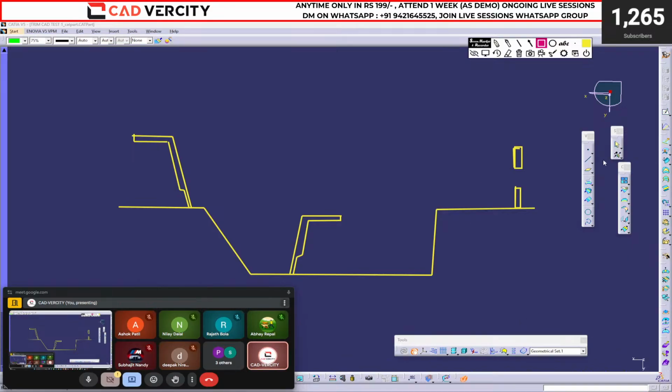See, this is a wall, and there is one hole over here. Tell me, and this is your MTD. Now where will the lifter, where will the slider be? Slider will be almost near to perpendicular to the tooling direction, on the right side of which you have shown undercut. Okay. So left side slider and right side lifter.